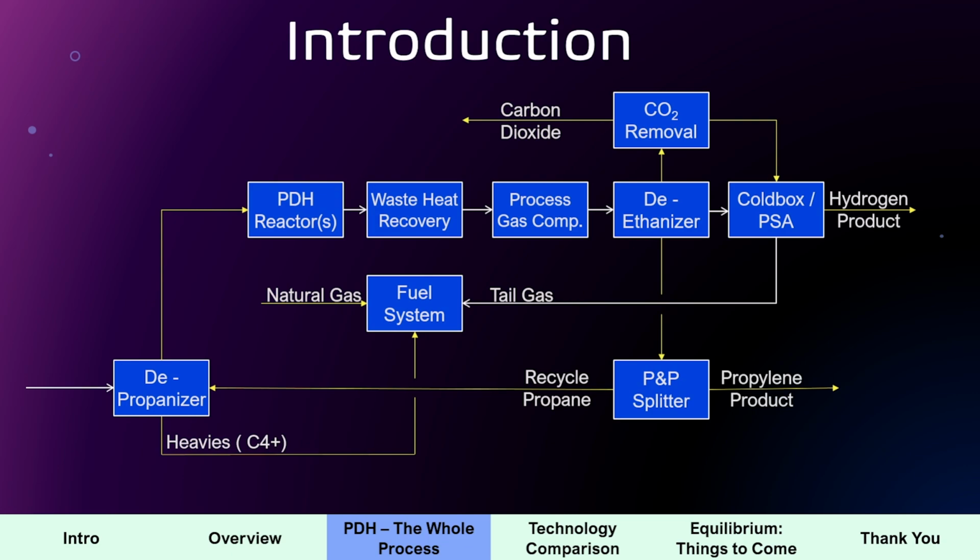If it's going to end up being used as a chemical grade for any other production, for example if I'm making acrylonitrile, they can be okay having low purity propylene. But if I'm directly making polypropylene, which is the second biggest polymer on a global level, it has a spec that needs to be 99+% by weight.